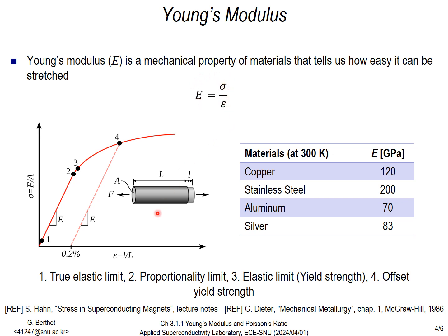Usually, Young's modulus is determined by doing a tensile testing. Basically, one can take a piece of material of defined size and apply a tensile load to stretch it until it breaks. While doing this, the stress applied and the deformation is measured. On the left-hand side, we can see the typical result of one of these tests.